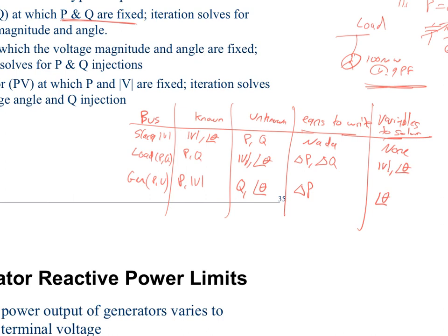Yes, sir? I guess I'm still confused with the capacitor. Just because I understand that, like, power zero doesn't consume any real power. Correct, power zero. If you're not given a voltage, does that make it like a load? If you're not told the voltage, you need to know what voltage that capacitor bank is trying to maintain. If you're not given that voltage, then it's all on. The capacitor is switched on entirely. If you're given a voltage that you're trying to maintain, then it's different.